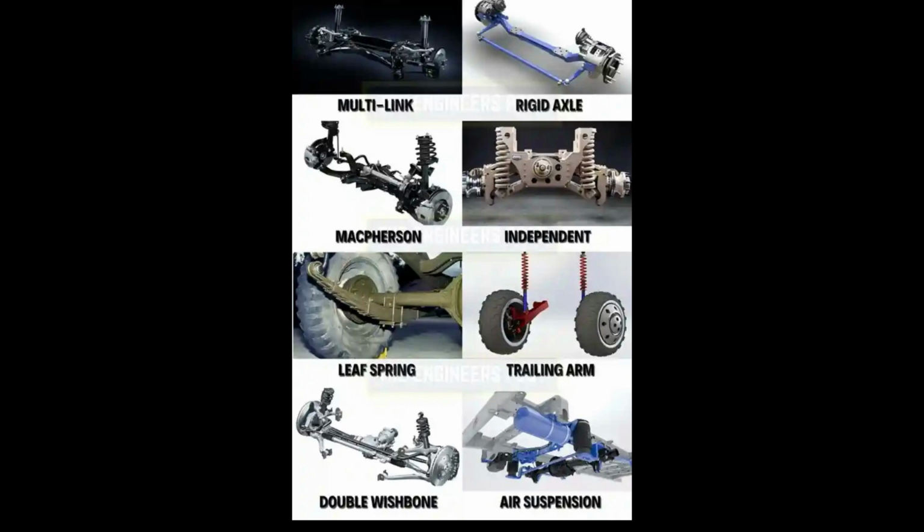MacPherson suspension. MacPherson is a suspension whose name is taken from its inventor, Earl MacPherson. Lots of cars around the world use MacPherson suspension. Many automotive manufacturers like this suspension because it has an affordable price and also has fairly simple components. The MacPherson suspension has an upright shape and is supported by shock absorbers, which are used as the center point of the corner caster in the car.